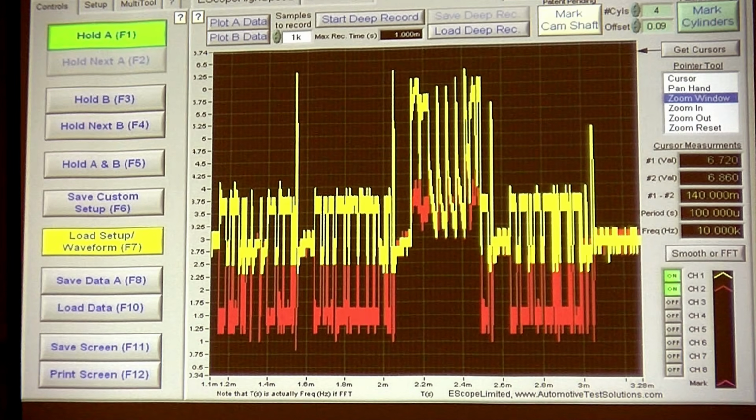Now I'm going to go look and I still got that stupid thing failing every minute or two. So did I fix it? No, so I've got to go get another module and unplug another one. Always realize if you unplug something and it starts ringing, guys, you did that. You took the termination resistor out, now you've got echo. Okay? So let's not do that. All you've got to do is bridge them. And with many of the modules, two wires go in, they come out the other connector. If you unplug the connector, wherever they went, that's an open circuit now. You no longer have termination there. Does that make sense to everyone?